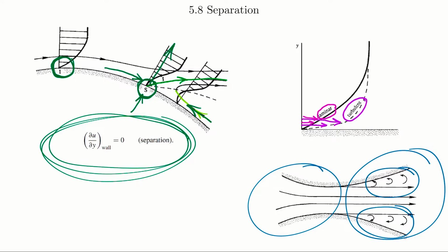Close to the wall. So our boundary layer equations would then only be valid as far down as the point of separation. Beyond our separation point, what happens is the boundary layer becomes so thick that the basic underlying assumptions that we made to come up with our boundary layer equations are no longer valid. Also, we can only do numerical integration in the direction of advection, along which information is propagated, but in a reversed flow region, that would actually be upstream. And so a forward, downstream integration of the boundary layer wouldn't work after the separation point.